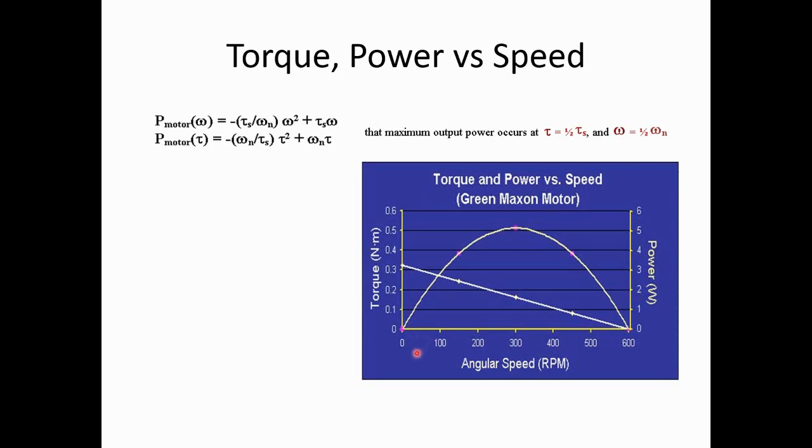It represents basically that, as a function of angular speed, you can only have a certain level of torque and a certain level of power. So for example, if we are at 100 RPM at this voltage, we can only carry close to 0.3 Newton meters of torque, and this is basically the level of power that we will have. So the power is a bit less than 3 watts, right? So this is a very small motor. It's just up to 5 or 6 watts, right?